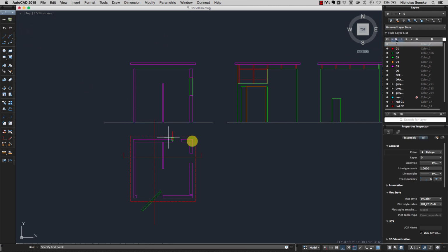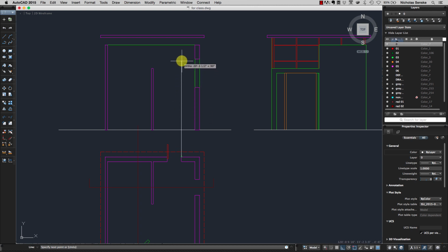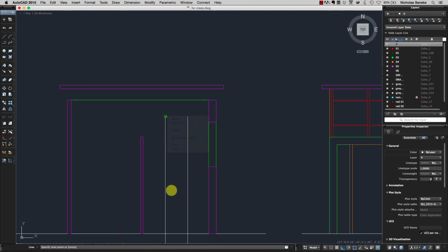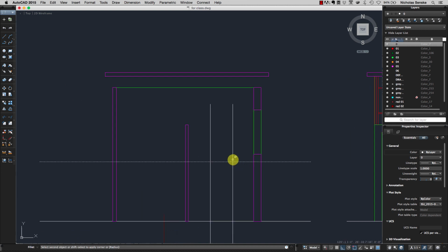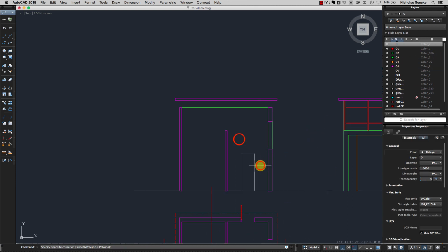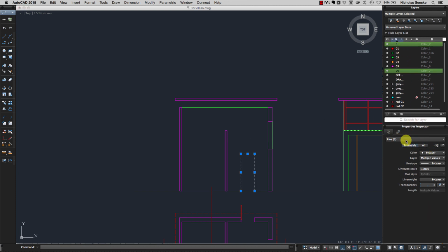I'm kind of cheating a little bit because I've got the drawing of the section already, but I just want to show you what you're supposed to get. Okay, so let me go ahead and offset this 8 feet, and we'll go ahead with the doorway in the drawing. I'm gonna do a fillet of radius 0. Just clean this up. For some reason it's not filleting. Well, let's trim it. Weird. Never had that happen before. Let's go ahead and trim. And this is the ground anyway, so yeah, and that's actually copied, so that's fine. Okay, and then this we'll pull this back to a red.